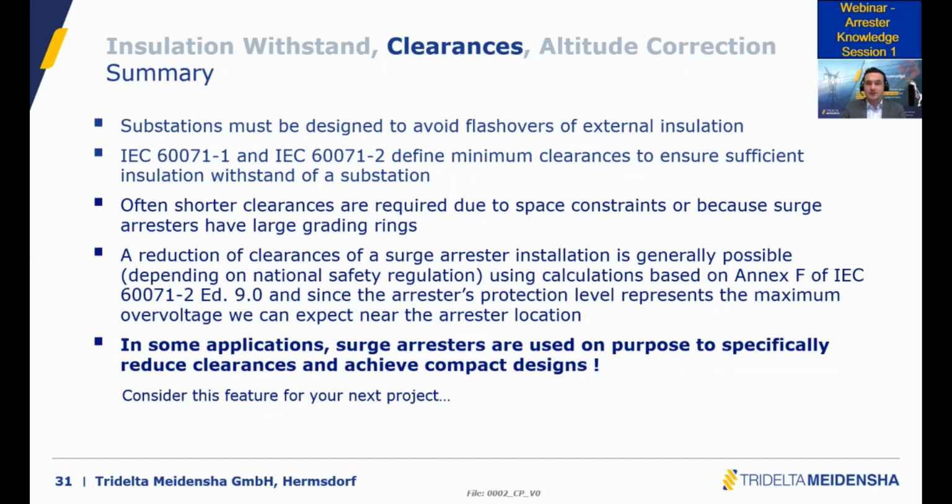I think the most important part of the conclusion is really to think twice when you are doing a system design or when you are defining the clearances for a substation or for a transmission line. It's always possible to improve the residual voltage and the protection level of the surge arrester. If you look at our catalog, or at any surge arrester manufacturer's brochure, you will see some standard values which are very common for a specific voltage.